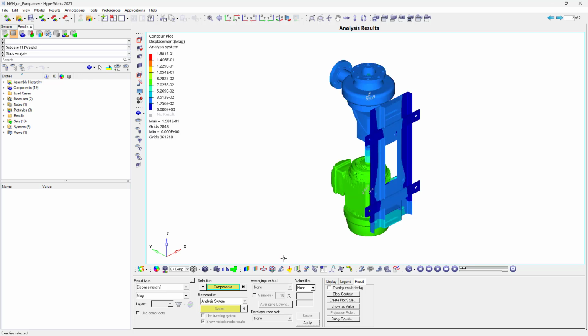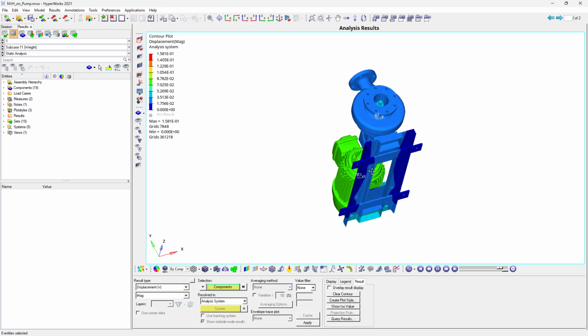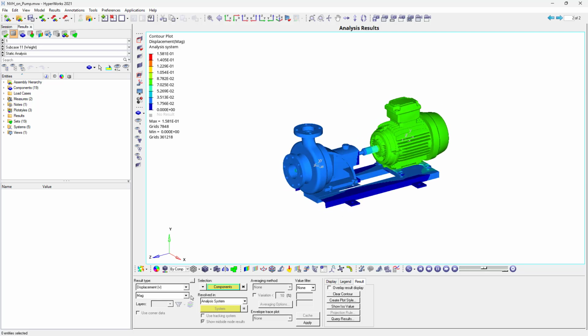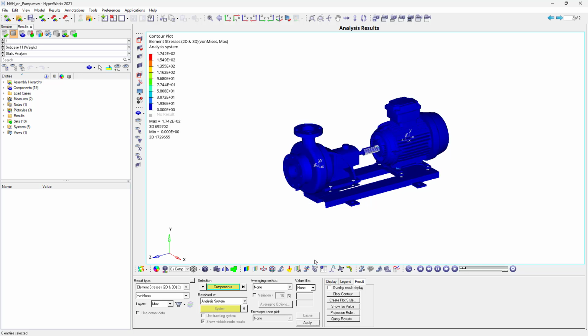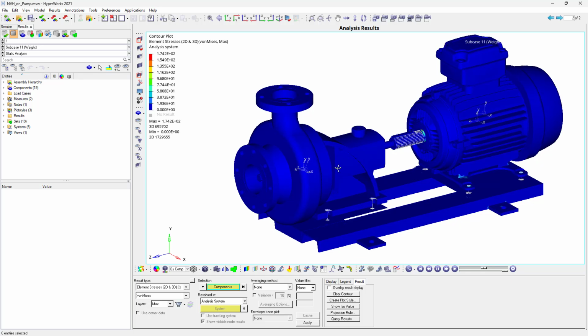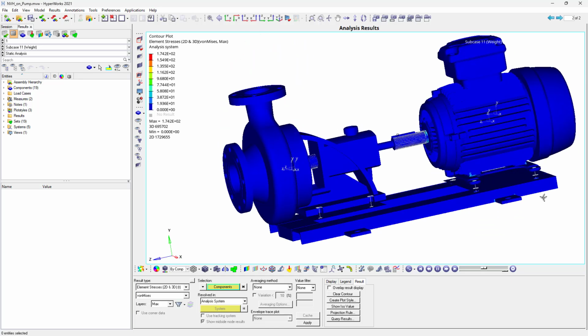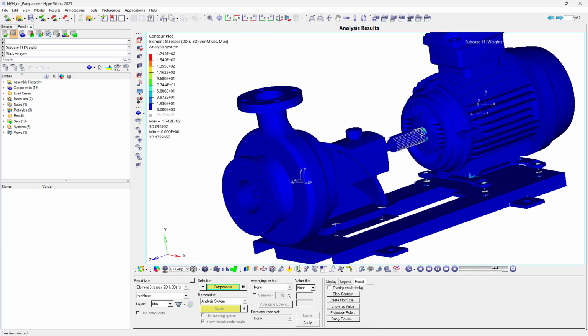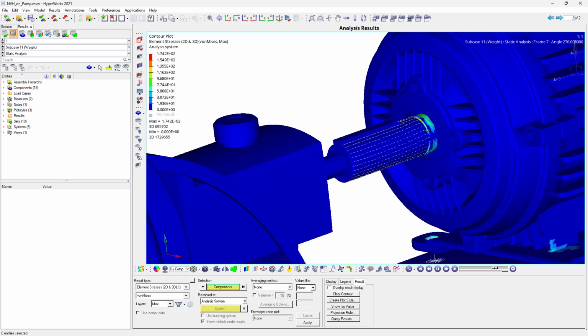You could see this is the displacement, least displacement we have, because as I said, it's just a self feed. It is not impacting much. Your model is also fine because there are no inappropriate movements. So stress wise, you could see it is 174 megapascal, so it should be the stress hotspot. As I said, if you zoom in, this is the region where we have the stress hotspot, right?